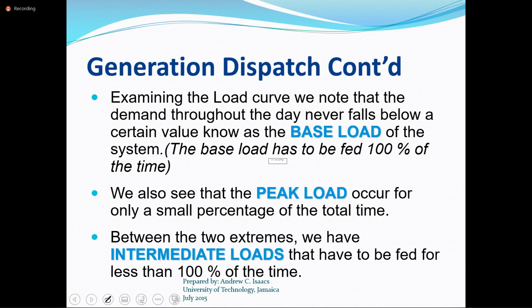So it's not looking per se at any individual load, and to say that we dispatch the slack would be incorrect, because the slack has to be constantly in operation, because all other voltages within the system are referenced to the slack bus.